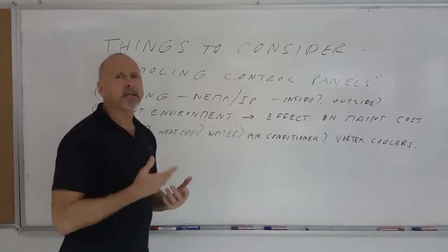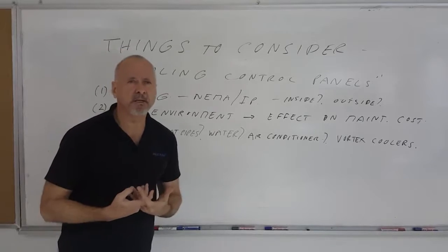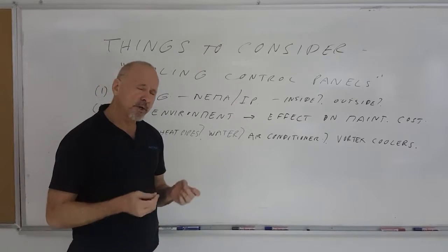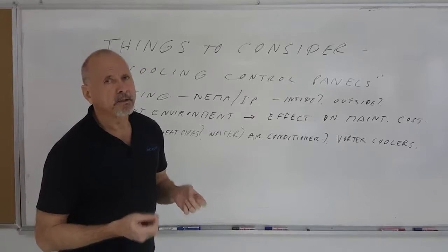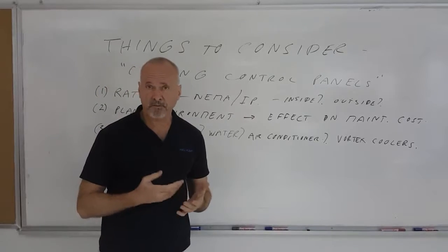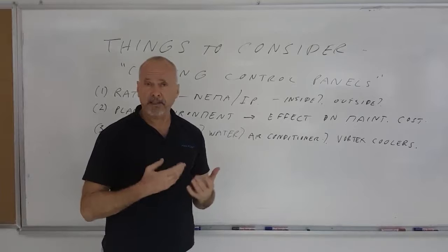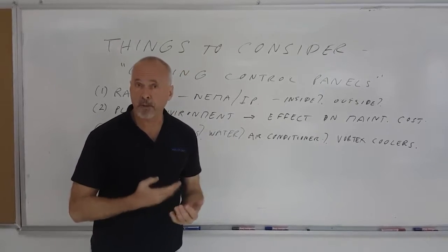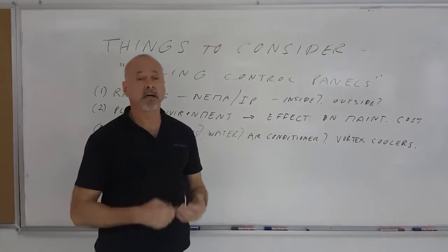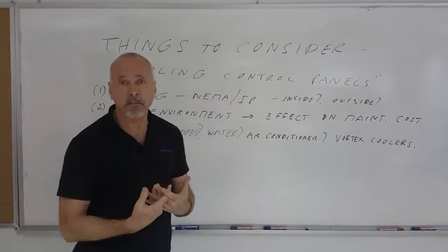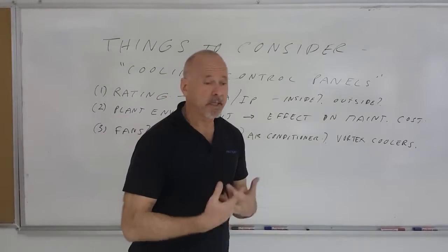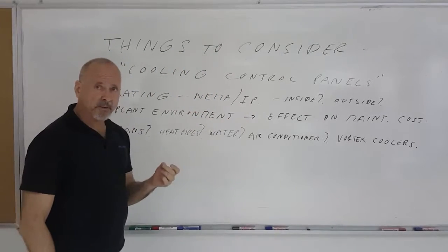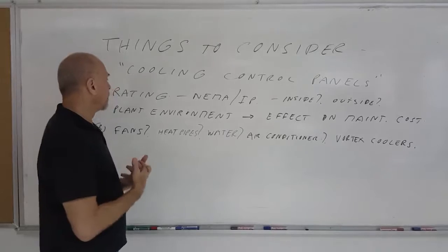But regular maintenance on air conditioners and fans involves basically changing filters. The dirtier the factory, the more often you've got to change those filters. And that's a cost. It's a cost of the filter. It's a cost of getting rid of the filter. It's a cost of maintenance time in putting that filter in. Time that could be spent better elsewhere. So the dirtier the factory, the more the maintenance costs go up.